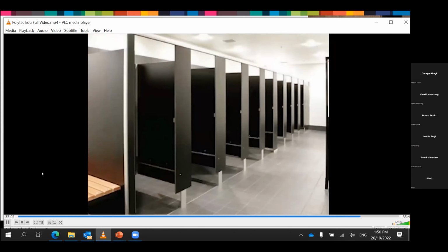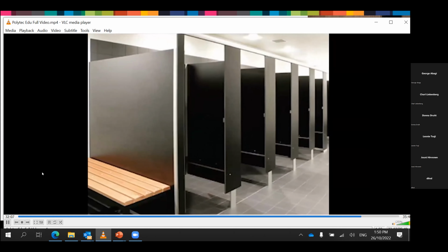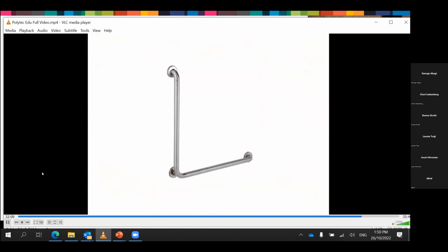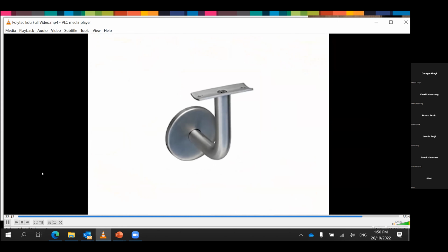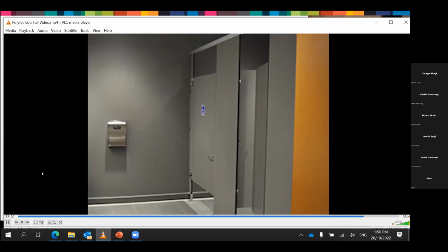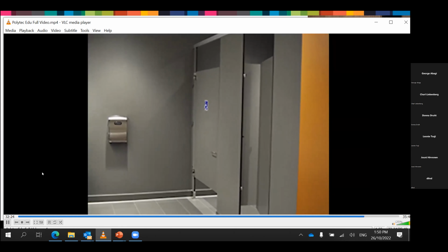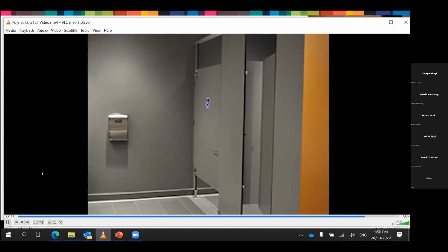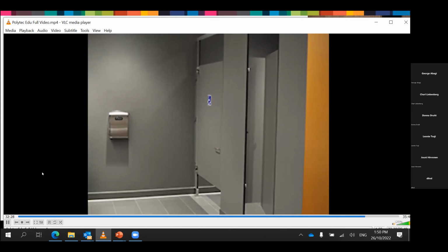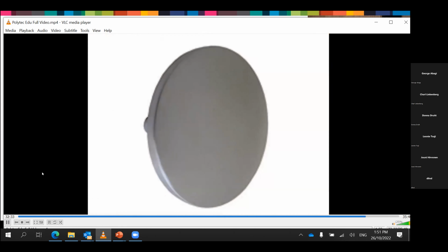To ensure dimensional stability, a top rail is required, which negates the flex in a product. Whilst grab rails are tested to withstand 1,100 Newton as required by the AS 1428, when installing them on a partition or divider panel, it is the responsibility of the installer to ensure both the partition wall and the screws used to fix the product can also withstand the required weight, not to mention other environmental conditions such as corrosion.